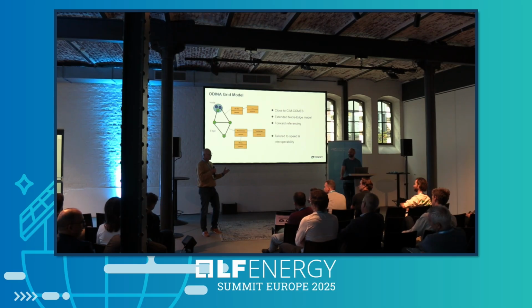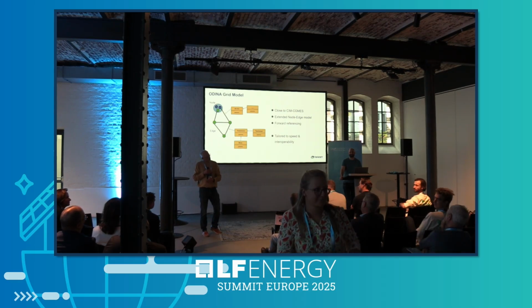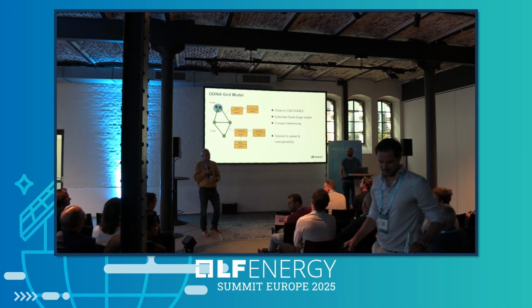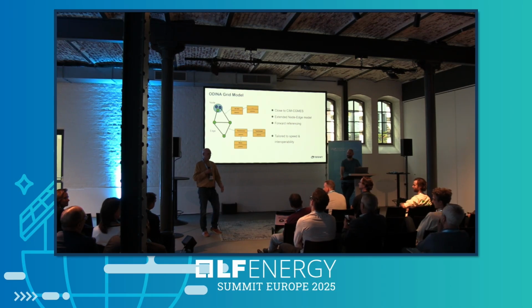But you cannot do that with optimization. You have to select all the hours with congestion, and then optimize those hours one by one. We cannot do all hours at the same time. Theoretically you could, but then you need a lot of memory and a good solver. So we have to do them one by one. But by using this trick of only updating the right side, it's still fast enough to do a few hundred or a few thousand optimizations for one year. So that's why we have basic linear programming.